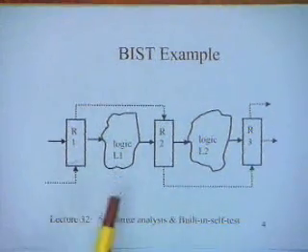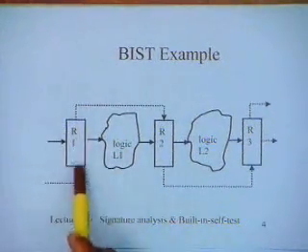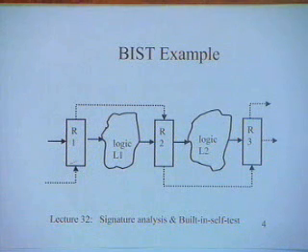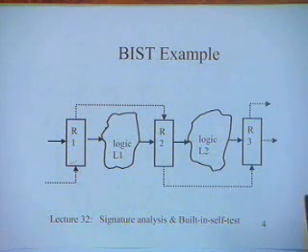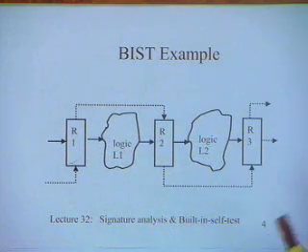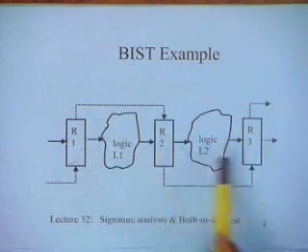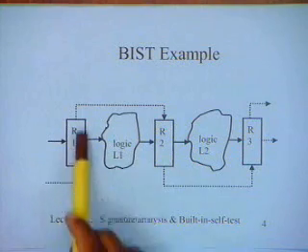Overheads are primarily the complex logic. Each of the simple flip-flops that you had in your circuit has to be replaced by this logic, which will give you these multi-mode operations. Normal mode operation, which was the PIPO operation, parallel in, parallel out, and also the operations in the test mode. Test mode is not a single mode, it actually has 3 modes: the scan mode, the PRBS mode, and the signature mode. So you have to make these registers complex, that is one. Second, of course you have to provide the scan path.